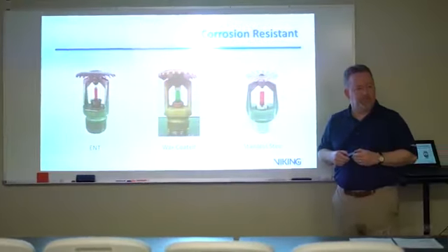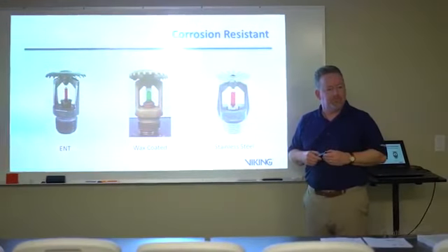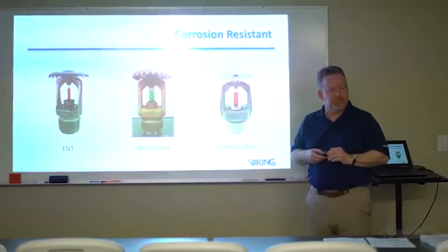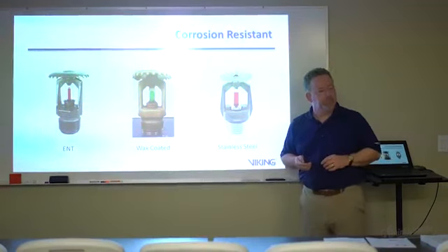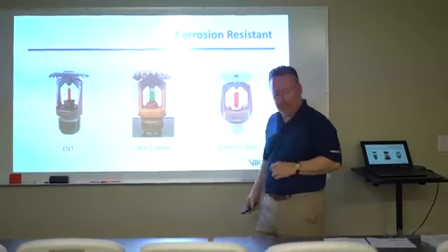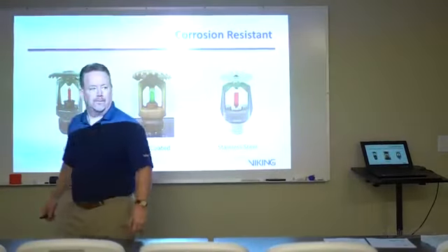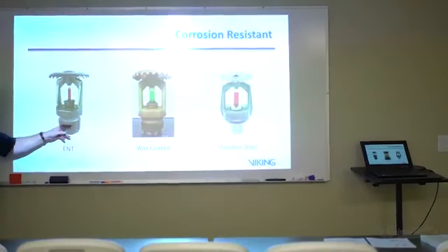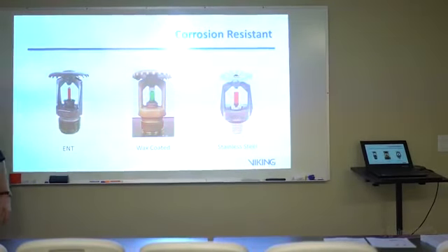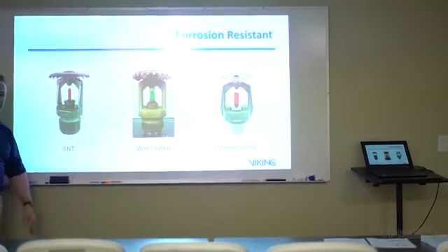The balconies down here, we've got a tremendous push for those. We're finding that with the poly-coated heads, the threads are not coated, and also along the sides when they put the wrench on it to screw them in on the balconies, we get corrosion at such an early stage that we're trying our best to move heads more and more to that ENT. So if any of you have properties that have any sort of outside area down here in South Florida, I highly recommend the ENT. That's the go-to head.